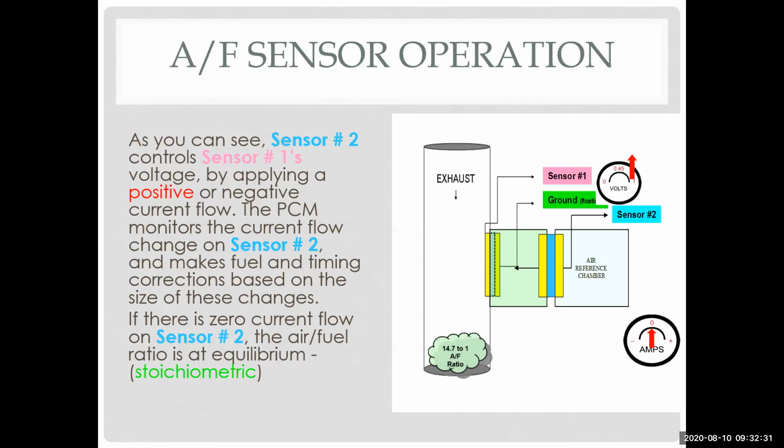Okay. So a couple of issues. Aeronautic engines tend to be turbine engines. Okay. So they run a very different fuel. Jet fuel is very different than gasoline. But their mixture is very altitude sensitive because obviously there's a lot less air at 40,000 feet than there is at sea level. So they do a lot of input controls for aeronautics. They don't do a lot of feedback controls on mixture because they're not trying to maintain one lambda.